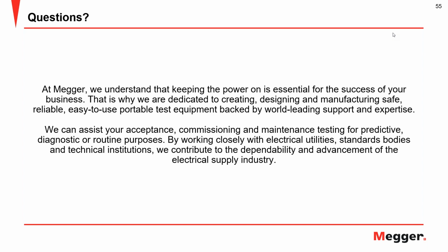Typically, how it shows up is you get an absolute tan delta value that is much higher than what you would expect for the pure solid dielectric insulation. And that's what gets some people concerned, and they say, well, the cable might not be good. It really has nothing to do with it.